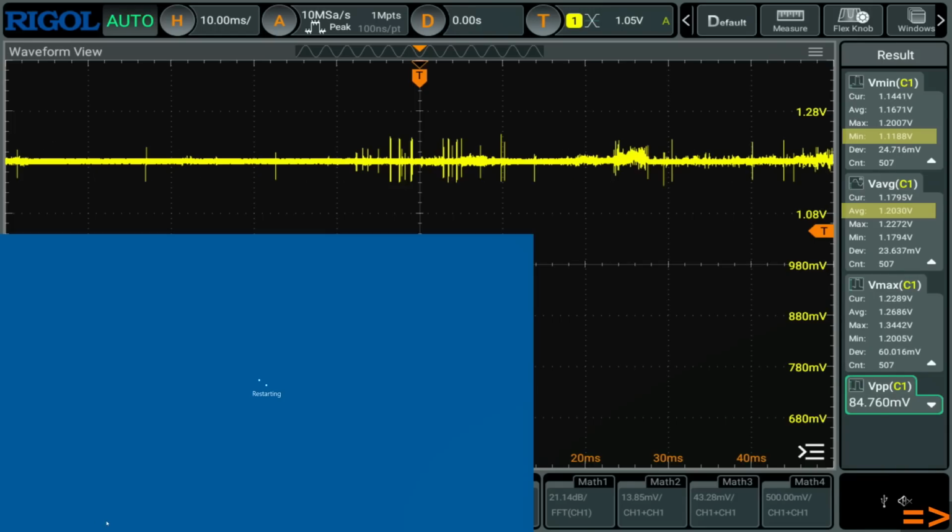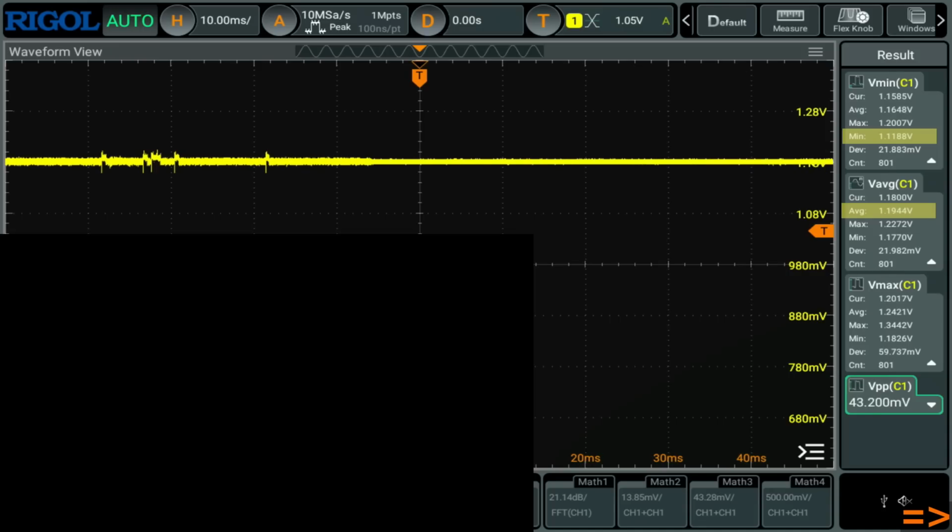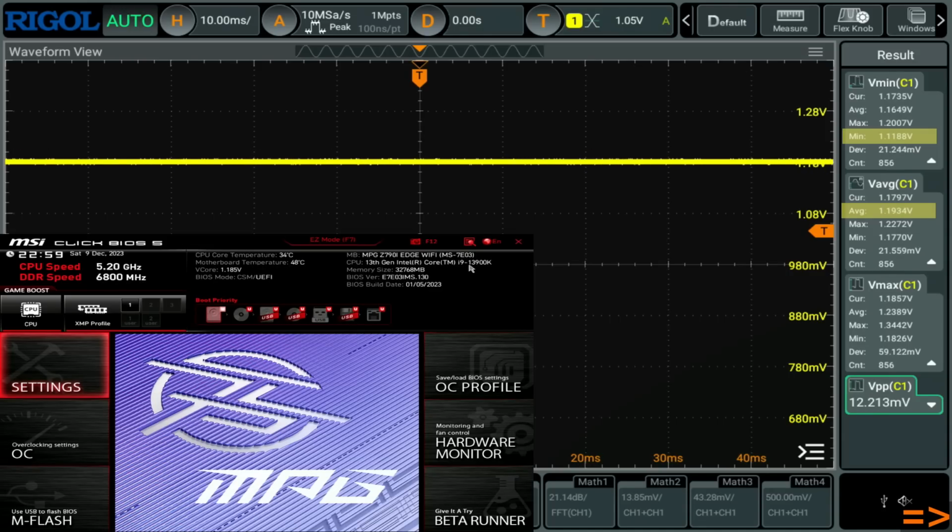And the reason I pointed out the VR Vout sensor on the board is because on some motherboards that sensor is inaccessible, which is kind of annoying. If you're trying to judge if an LLC setting is overly aggressive or not, because you just don't know how accurate the onboard voltage sensor is. Like on some motherboards, it's really bad, because the various motherboards will have different amounts of voltage drop across the CPU socket, and then where the Super I/O,